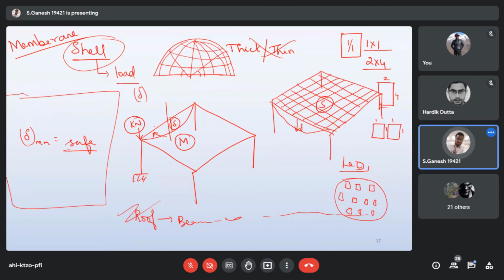But the concept of application of plate, application of surface, application of floor load is different. So that you understand, don't confuse it: either if I design as a plate, self weight should be ignored, or if I design as a floor, self weight should be added. It's not like that, right? So please understand, self weight is common for all kinds of structures. It is there in both, whichever application you are choosing.